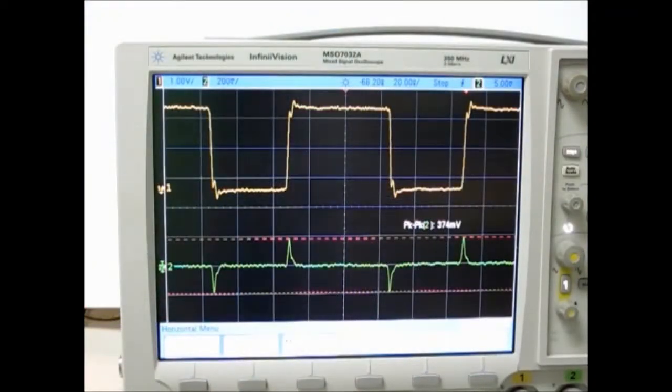As you can see now, the polarity of the near crosstalk spot is the same as the previous narrow copper line, which was shown earlier in this video. However, the spot level is smaller now, which is 374 mV compared to 394 mV from the previous narrow copper line.